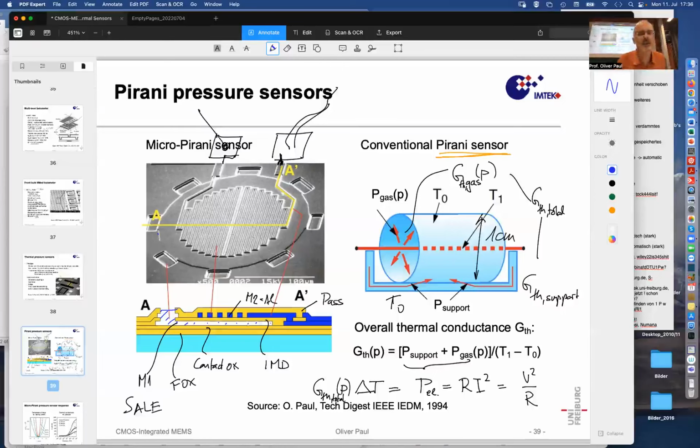And you see that we have a distance to remove metal of 100 micrometers horizontally. Now, when you go back to chapter 2, 100 micrometer of sacrificial aluminum etching is not so much. It's easily done with the commercial etchant that we used. So all we had to do was to design that structure, kind of unconventional design. A circuit designer would say, what kind of a funny structure? That can't be a circuit. Yes, indeed, it's not a circuit, it's a sensor.